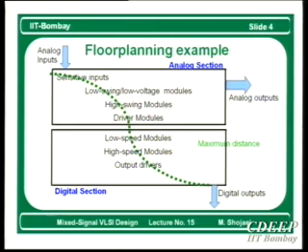So now how does this interaction happen? Interaction between these two modules happens in different ways. One is from interconnect lines where you have coupling capacitances. One way is through the substrate, because after all these modules have a common substrate. If you are able to have two separate wells, that's much better. But usually it is not possible. Therefore, if the process forces us to have a common substrate for everything, this common substrate is a source of noise.